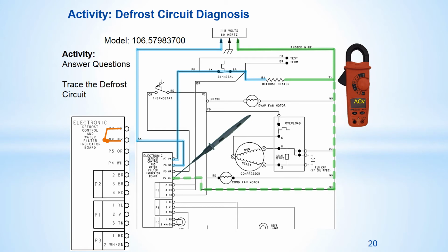Where could you place your red meter probe to check for source voltage? The answer is P6 on the ADC board, the black wire. The voltage level, polarity, and proper ground measurements can all be taken between these 2 points and cabinet ground. If these are incorrect, you will then need to access the power cord or the wall outlet to determine the source of the issue.